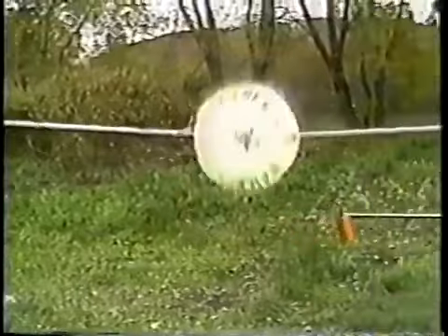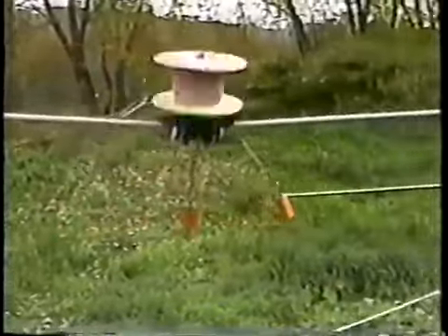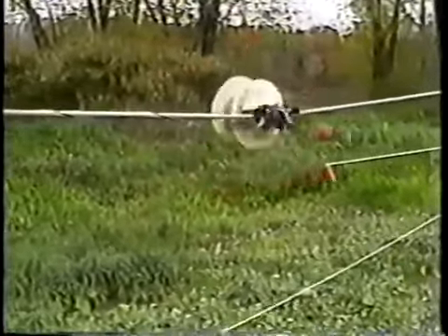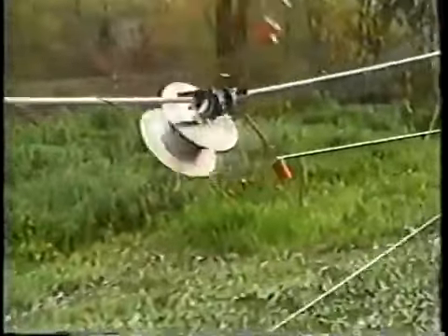One disadvantage is that a buried cable may be subject to damage, and each additional splice for repair can significantly reduce the signal strength. One method to reduce this kind of damage is to run the optical fiber cable in the air, supported by a power conductor or perhaps the ground wire.